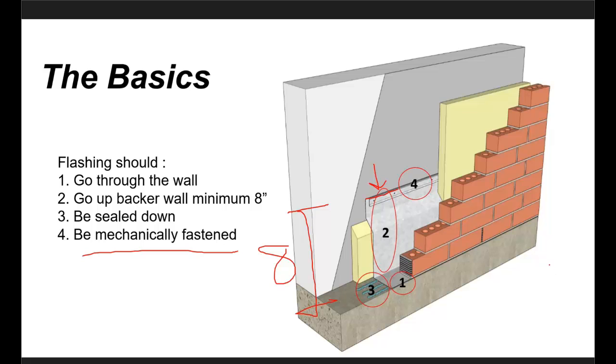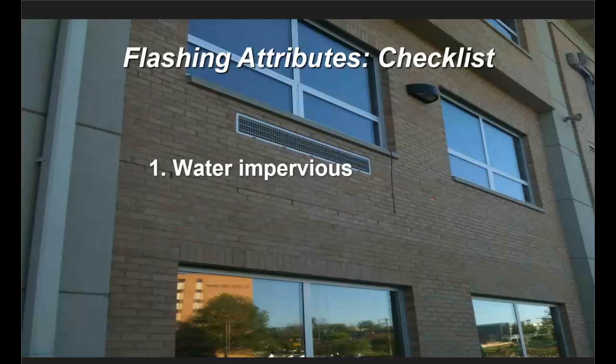If there is ever an option to shingle your air barrier over top of your flashing, that's the best case. Because when you attach something on the face, like flashing is, it's technically a reverse lap. So if you could bring your air barrier over it, you would want to do that. I know it's not always possible.